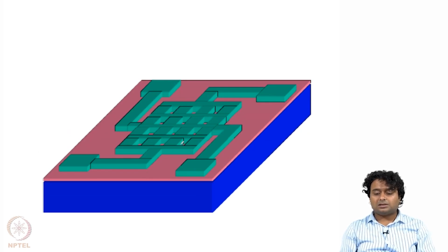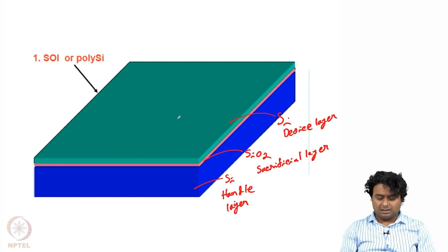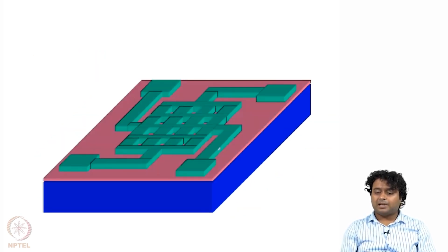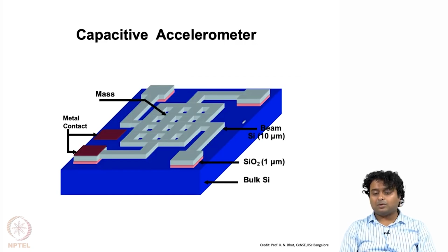Now, we have discussed lithography in module 3. There we saw how we can make a pattern on silicon or on any substrate using photolithography and e-beam lithography. And here you see that using lithography, from this structure we have etched the silicon according to our requirement or our design, and we have got this structure. After that, if we dip this sample into buffered HF or BHF, that will etch away the SiO2 part wherever it is exposed.